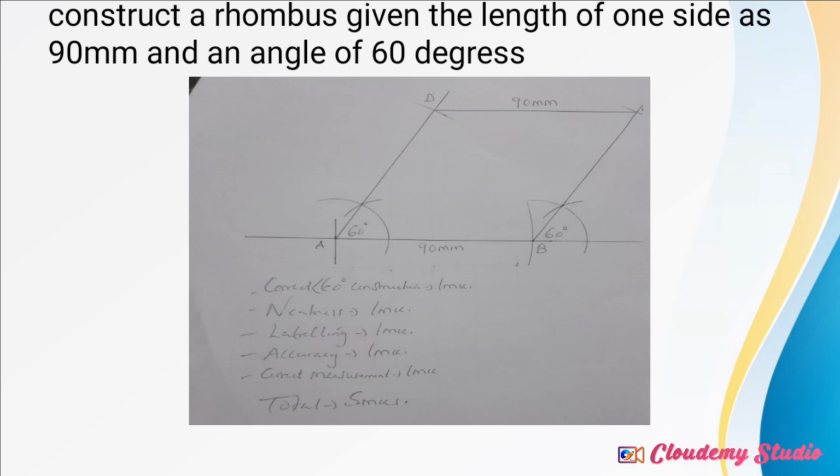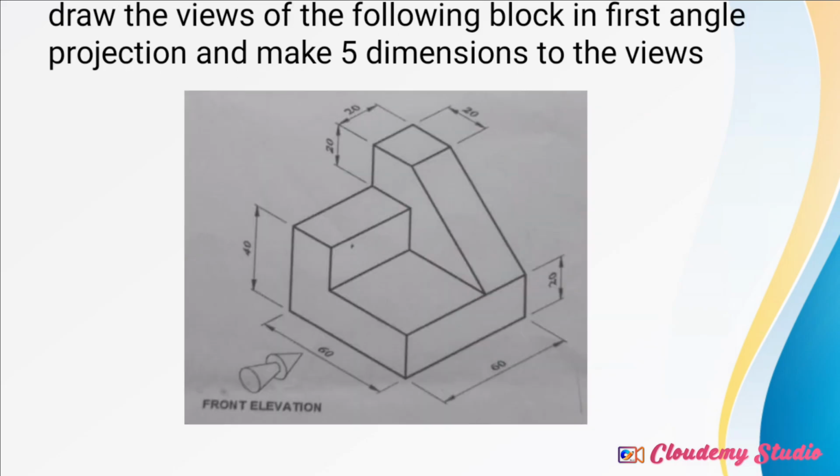Then you go to the last question for section B, which was: draw the views of the following block in first angle projection and put 5 dimensions on the views. So this was the view, and you are given the front. You consider that which was on your left side as the front elevation. If you're given these questions, you have some very key points to consider. You have to look at 5 major dimensions. There are 5 marks, 1 mark each for a person who dimensioned the sides of those views, giving at least 5 of them.